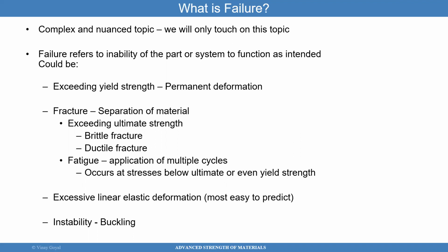Exceeding yield strength is one type of failure issue, and exceeding yield strength can be a problem a lot of times. But a lot of times, it's very difficult to actually make sure it doesn't happen. In those instances, we evaluate yield strength. If the yielding occurs locally, you could evaluate it to make sure there's no functional performance issues. You want to make sure that there's enough fatigue life if it's yielding locally, and there's no gross new failure modes being introduced by the yielding.